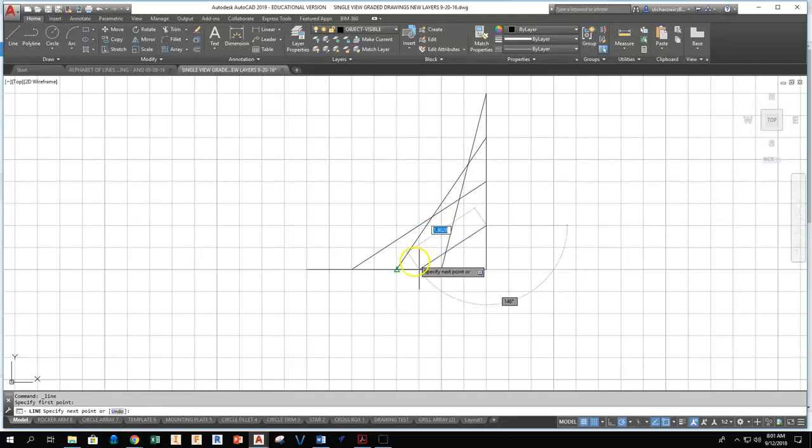This time I sat there long enough that it recognized that I wanted to be in that position. Sometimes what you need to do is just sit in a position on the AutoCAD screen long enough, because if I didn't sit there long enough, it jumped back to the endpoint. If I very slowly make the move, the extension turns on, and it will jump to the position where you want to be. The time that you hover over an area, AutoCAD is reading information.